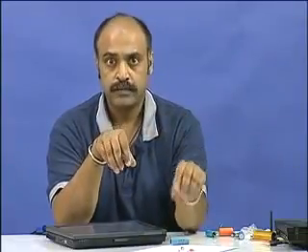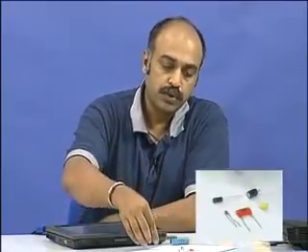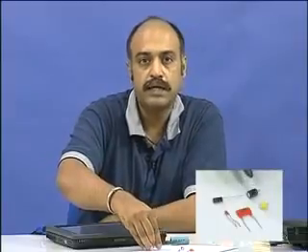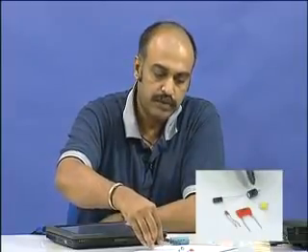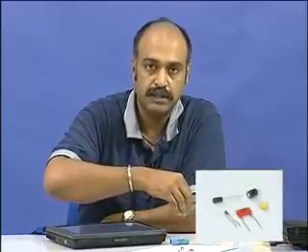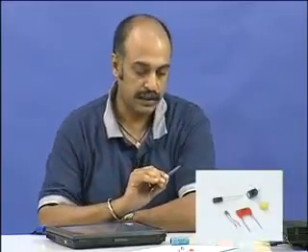The second value that you will see on the nameplate is the voltage that it can withstand, because beyond that the dielectric will break down, and then it will get damaged. So, you should not apply a voltage to the two terminals which is higher than what is written on the nameplate. Which means that this is a 4.7 microfarad, 100 volt capacitor, and you should not exceed the voltage of 100 volts here.